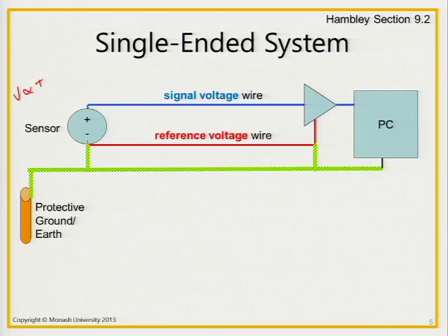Now, for a whole load of safety reasons, it's a really, really good idea to connect pretty much everything you can to a protective ground or earth voltage. So all of these here, and what typically happens is you want the voltage to be the same everywhere, right? The same 0 voltage everywhere, because then when you measure any voltage, it'll be relative to this green ground wire. And here's that copper stake that I was telling you about that you might have in your house. There's an equivalent in the industrial sense.